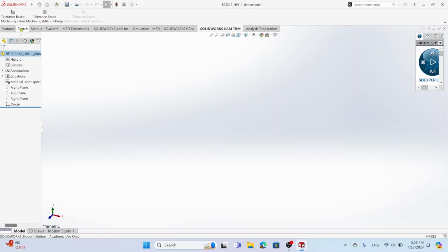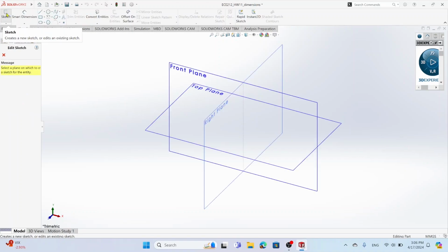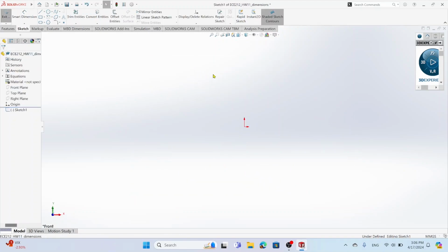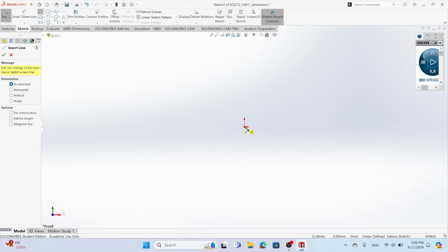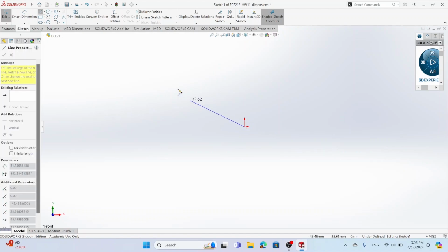We will just do a sketch. We will do nothing more than a sketch. So let's do a new sketch, front plane. So I select the front plane. I will do a sketch for dimension BA, and this is up to you to decide where you want to put that 0. Let me put that 0 at point A because that's the point that we have the information.